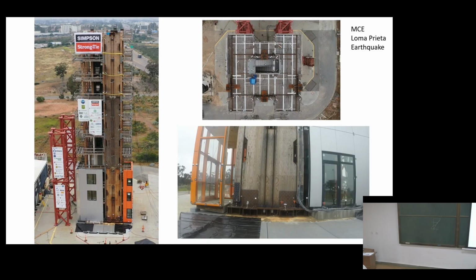So even after Loma Prieta earthquake at MCE level, there was no damage. Yes. As I have done work on non-structural elements, I found that in the bottom story we could not find much amplification. But as we go to the top floor, we found dynamic amplification. Yes, that's a great point. However, this is not just the bottom story, but 4 stories tall, non-structural elements were. So this is 4 stories here.